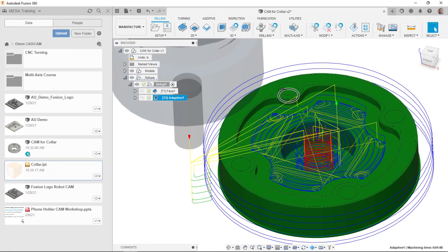So you can see here is a very simple process. This would be very easy collaboration with someone else in your company or outside your company that is maybe doing the CAM process for you. So you can see the send to Fusion command is really nice. If I have a new version, just make sure I hit upload new version. And then anybody that's consuming that data on the Fusion side will get those little triangles saying, hey, an updated version is available. Do you want to update? And of course you do. So you should see that that works fairly smoothly, fairly easily.